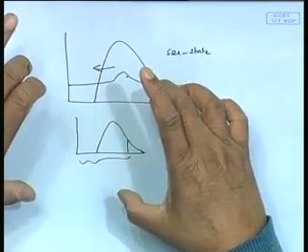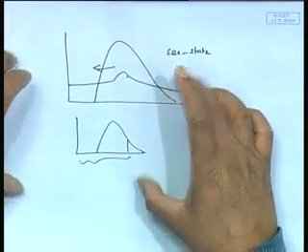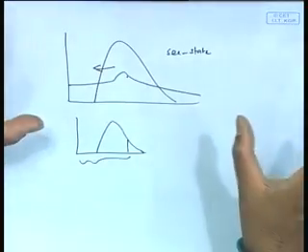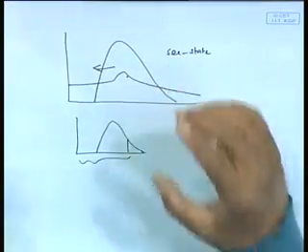But what we understand is the procedure to calculate response in irregular sea is absolutely simple, straightforward algebra, nothing to it. Okay, multiply. So, therefore, you have to make sure you are taking the proper inputs. What is important, of course, is studying those responses eventually. Is it good? Is it bad? Is your ship going to behave properly, etc.? And these days it is becoming more and more important. And then going back, you find out the most difficult part in this still remains getting the RAO. This is where efforts go. Those who are not in the subject, practitioners, look only at the last 1%. Those of us who are inside, we talk about the RAO mostly.